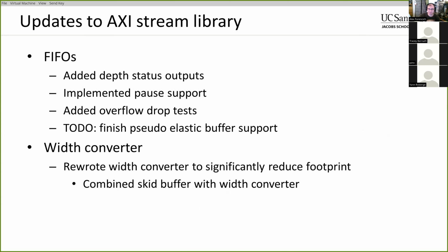Right. So to support some of these modifications, I've been making some changes to the AXI stream library. I added depth status outputs to the FIFOs, so both the synchronous and the asynchronous FIFOs now have outputs that indicate how much data is sitting in the FIFO.